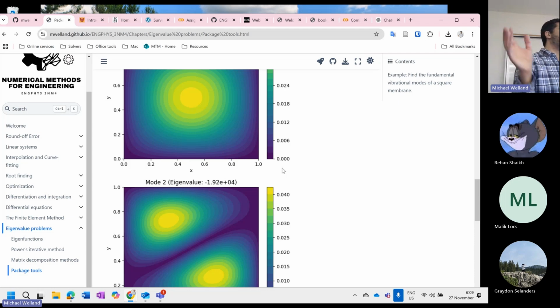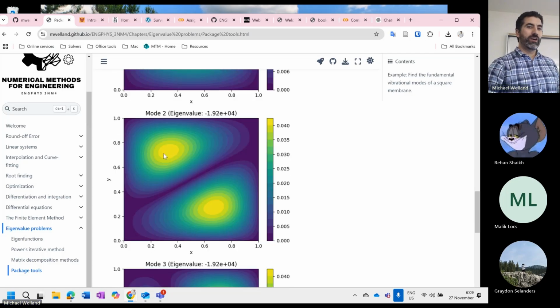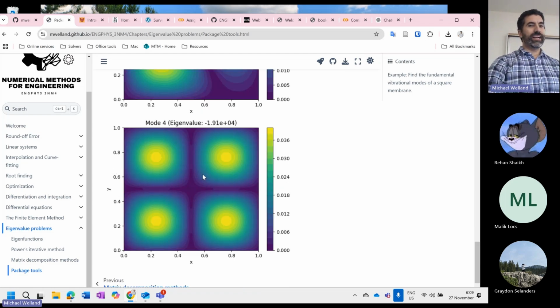So there are some examples, and I'd love to get this equipment. What you do is you get a big sheet of metal, you put sand on it, and then you start knocking on it with a mallet, and it conforms. All the sand naturally aligns with, I think, the nodes. Depending on your frequency, you would have all the sand migrating out to the side. If you do it a little bit sharper, you're going to see it defining this line here, because all the sand is basically being pushed off by the modes and collecting there. And then even harder, and you get this nice quadrant pattern.